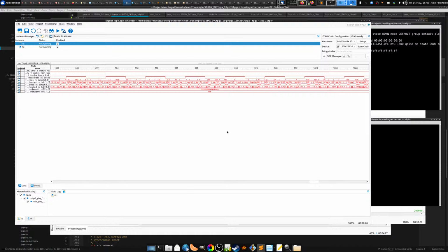It's continuously bit slipping. Hang on, I'm going to try a different NIC on here. It's possible that the Mellanox NIC that I have is causing trouble. I'm going to hook up an Intel 10G NIC, and we'll see if this is a little bit better behaved. So the main thing that I'm looking at here is the fact that this bit slip signal is toggling.